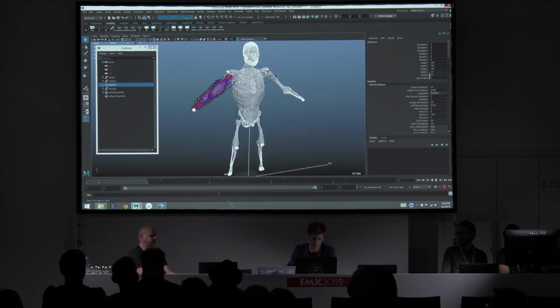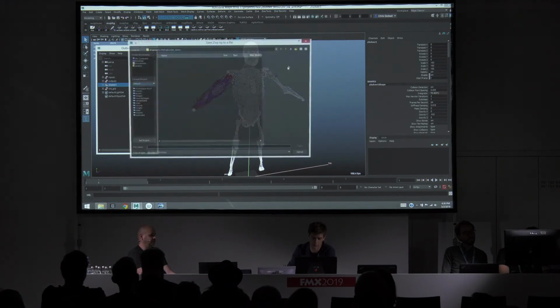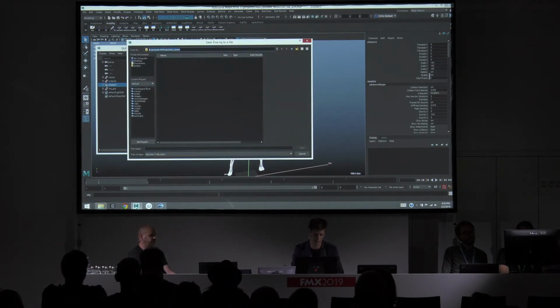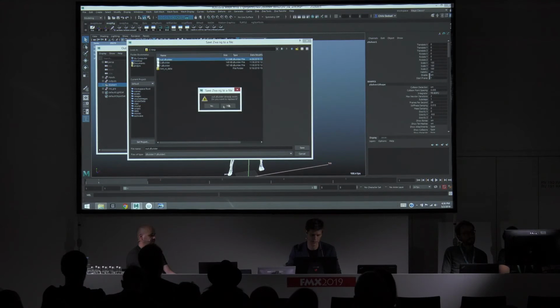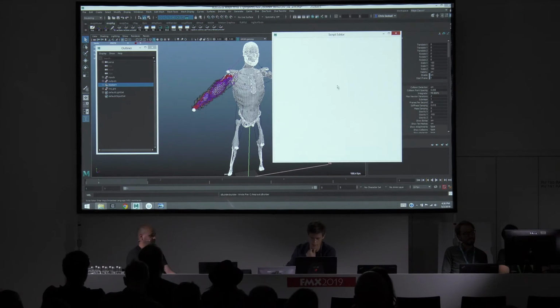So if I want to copy the entire setup, everything to do with this solver, I just have it selected, and then in the Ziva transfer menu, come down to Ziva rig, I'm going to save it. And I'm just going to send it to a temp directory. Call it out.zbuilder, hit save. And then wait a little bit.